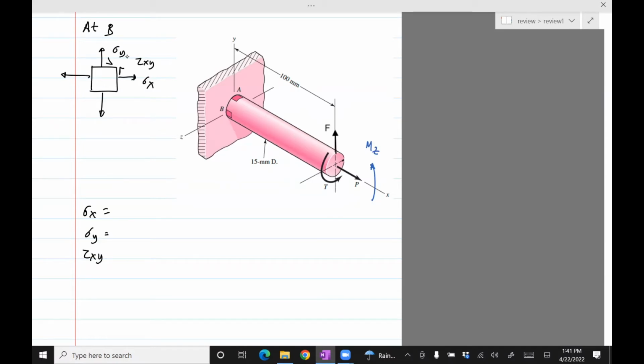First, let's figure out. One of the two ways: you can ask yourself, what are the stresses in the sigma X direction, and then cycle through all those moments and forces and see what contributes. The other way to do it is to look at F and ask yourself, does F lead to sigma X, sigma Y, tau XY, and then put the value. So either way is fine. Let's just do the way we've been doing, which is let's try to identify sigma X by cycling through all the forces. So let's ask ourselves, which of those four things over here will contribute towards sigma X?